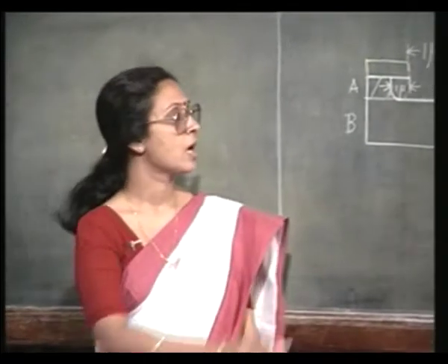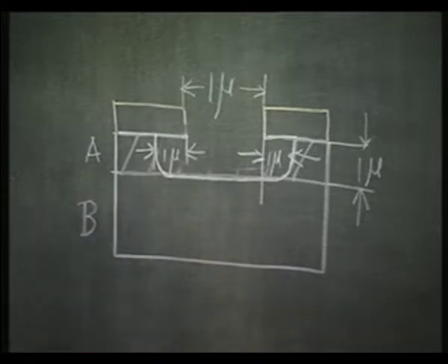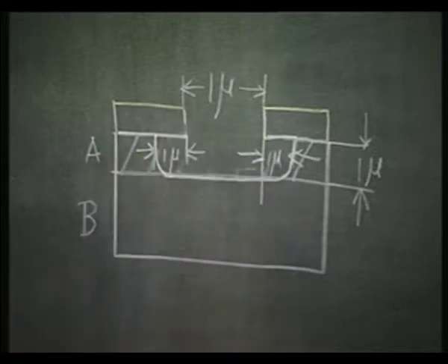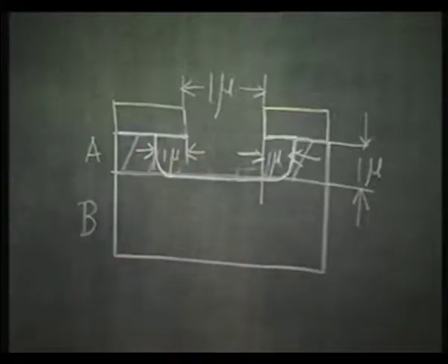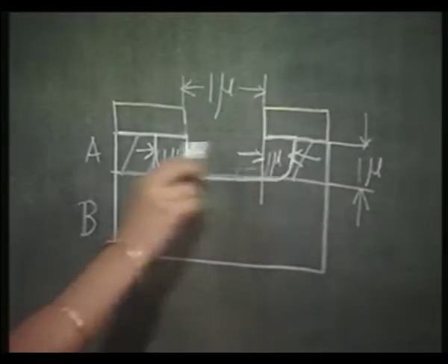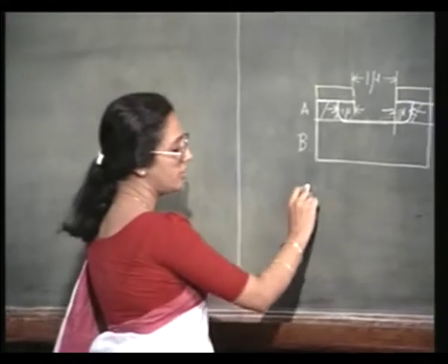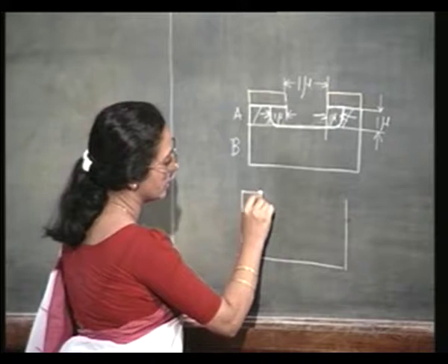So, what happens? From the instant I have reached the interface between A and B, the only etchable surface in the etchant solution is the sidewalls. It does not etch B. So, the etching virtually stops here, but it can keep on etching the sidewalls. So, what will happen? If I keep it for a longer duration than is necessary, what I will have is something like this.